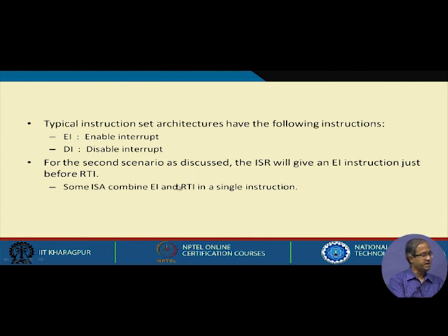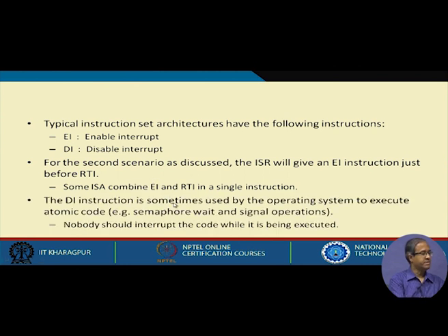Some instruction set architectures combine EI and RTI in a single instruction. So, when you do a return from interrupt, interrupt will be automatically enabled, you do not need a separate EI. And the DI instruction can be used for some other purposes also, like sometimes the operating system can execute DI to prevent interrupts from coming.